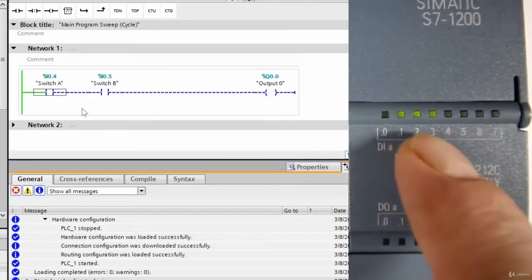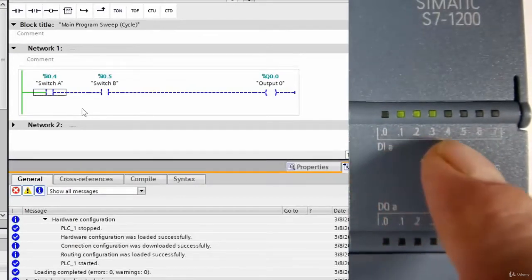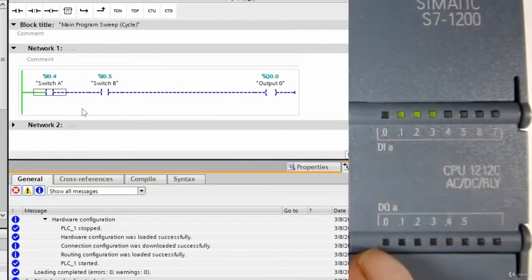Negate these guys, so these are garbage, right? Because I broke those off, so it looks like 1, 2, and 3 are set in the on position. But we're going to look at input 4 and input 5 on our LEDs. We're going to look at this LED right here for our output 0, and those are going to correspond to these guys right here. So I'm now going to switch input number 4, and you should see this guy goes green. Oh, that's nice. Excellent.